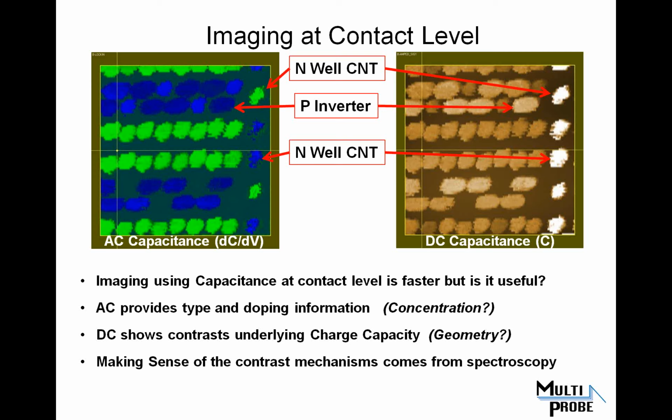And remember that this is a really simple sample to make. It takes just a little bit of delayering. You can spend just a few minutes to get down to contact layer, or a few hours depending on how careful you want to be with it. But everybody routinely makes this type of structure. It's roughly exactly the same as the type of structure that anybody would make in order to do nanoprobing on such a device.